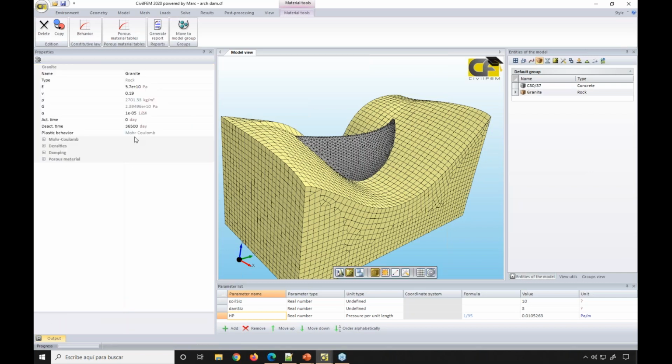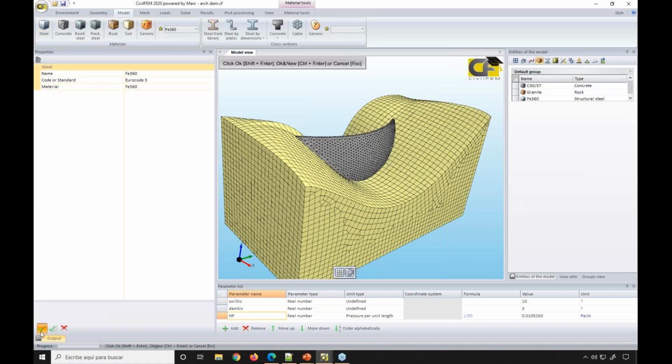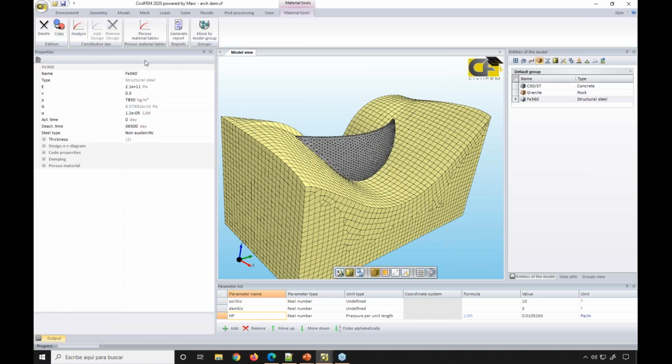Usually, once you select one of the material models, you will need to set different properties. By default, for Mohr-Coulomb and Drucker-Prager, there's a cohesion and friction angle. Some of the properties are already predefined, but you must change them to set the ones that you have from your data.